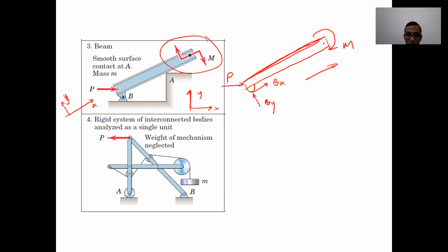So you can use this kind of coordinate. Basically, the main important point of Px, Py in the pin joint is that both are perpendicular to each other. As long as you put both perpendicular to each other, whatever direction that you want to use is supposed to be okay. Do you get it?